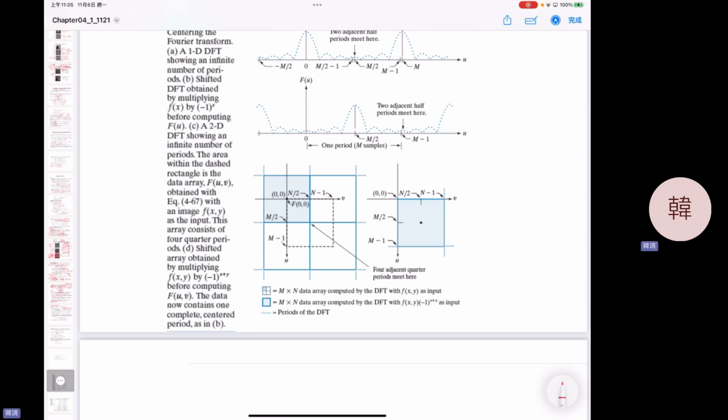How about this one? This one is a high-pass filter, but partially low frequency components remain, because it's an offset high-pass filter. So you can see the low frequency component is still maintained, but the high frequency component is enhanced. So you can see it's very clear for the detail. And the color is not like this, with no DC value. Similar to the original one, but this one is for smoothing. So it's very easy to see.